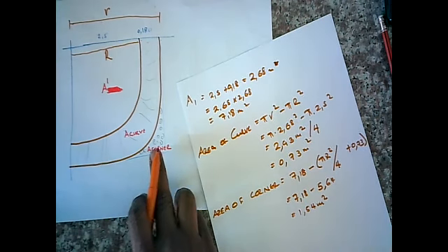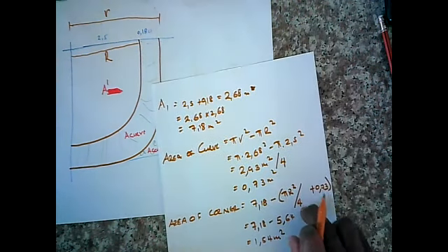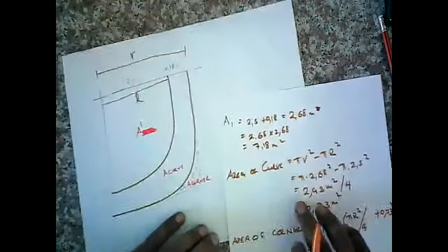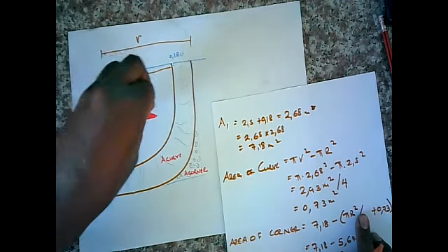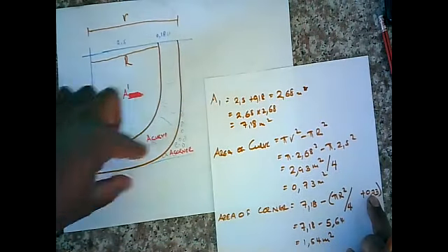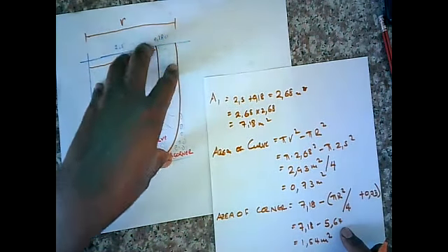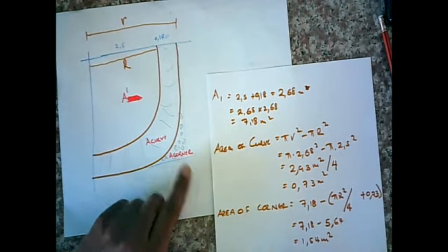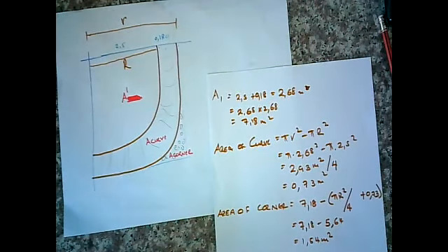All right, so I found this particular area there. All right, why 4? Because quarter, right? That's for the entire circle, from there to there. But I just need that part, a quarter of it. Then therefore divided by 4 plus that section there, right? Gives me 5.46. We know the complete area, and therefore the little portion that we're looking for is 1.54 square meters. That's it, right? That's the most difficult thing about roads quantities,